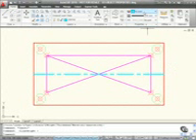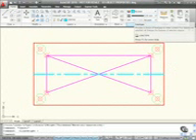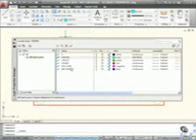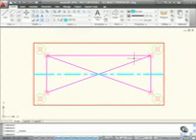So we've looked at color, line weight, and line type. Let's say that I want to change the line type of these two polylines. I don't want them to use the continuous line type, but I don't want to change the line type here in the Layer Properties Manager. You can see there, polyline is magenta and it's using a continuous line type. So what we'll do, we'll just change them individually by selecting both of them, like that, and then clicking on the line type here.